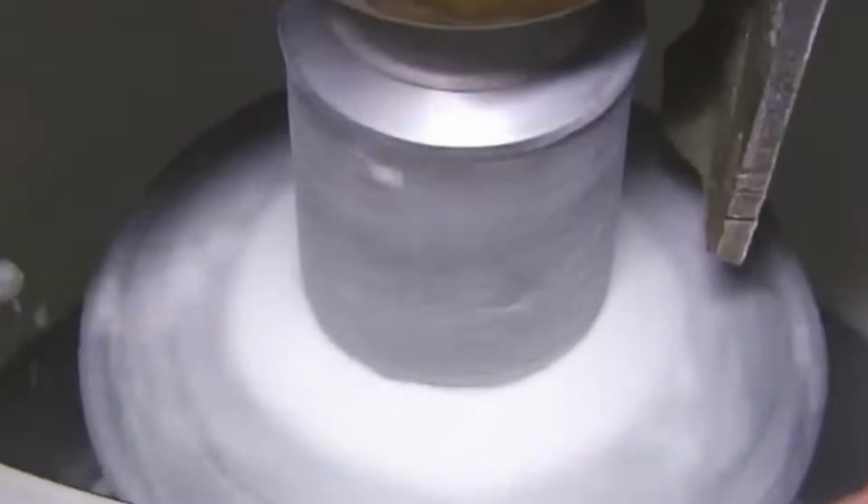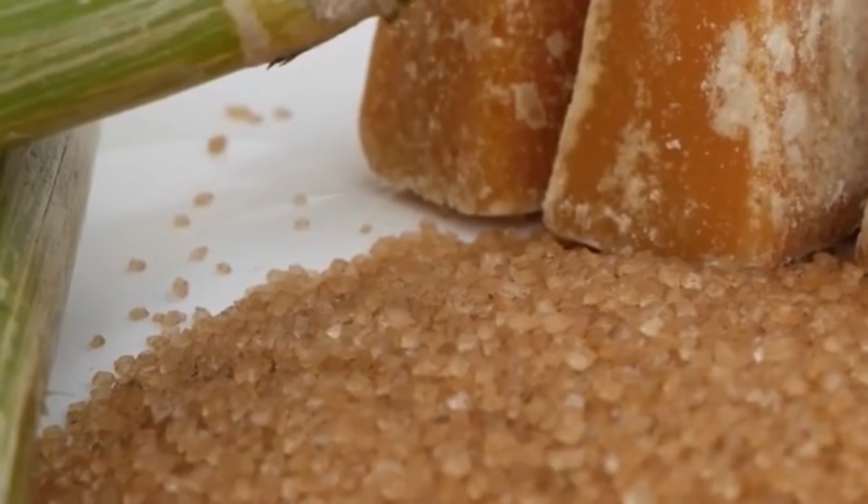Chocolate chips are dispensed through vibratory feeders equipped with mass flow sensors. Feed rate is adjusted automatically to match dough throughput. Chips are gently folded into the dough using planetary paddles to preserve shape and prevent smearing.